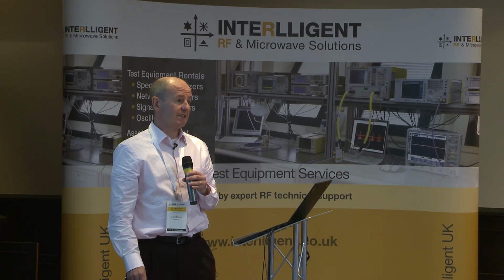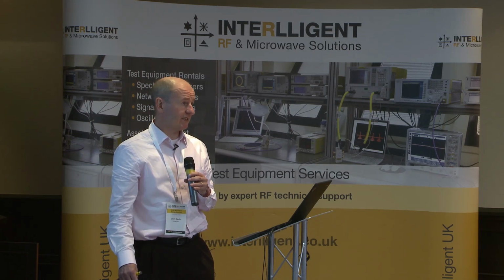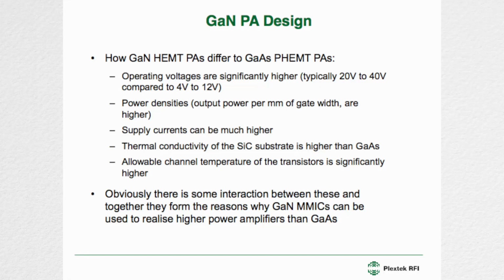The thermal conductivity of the silicon carbide substrate, and all of these processes that I'm going to show you examples on have a silicon carbide substrate, is much higher than for GaAs. The allowable channel temperature of the transistors for reliable operation is a lot higher. And together, these features mean that GaN MMICs can be used to realize high power amplifiers with a much higher output power than you can with gallium arsenide.